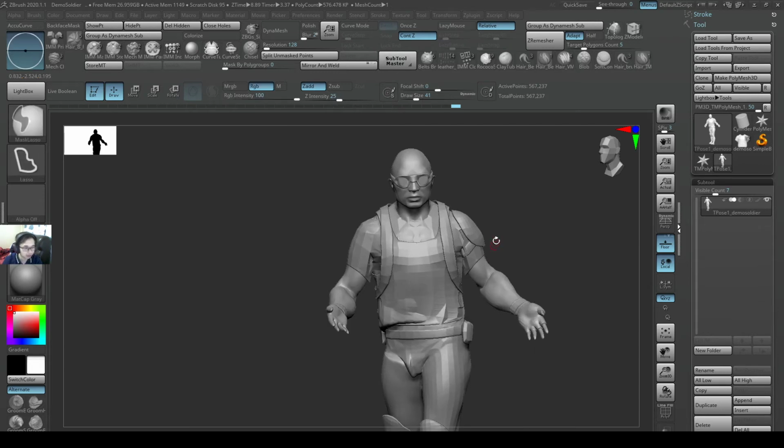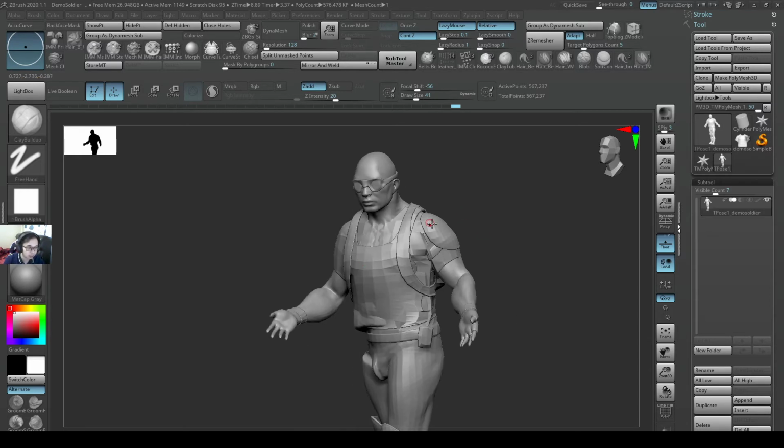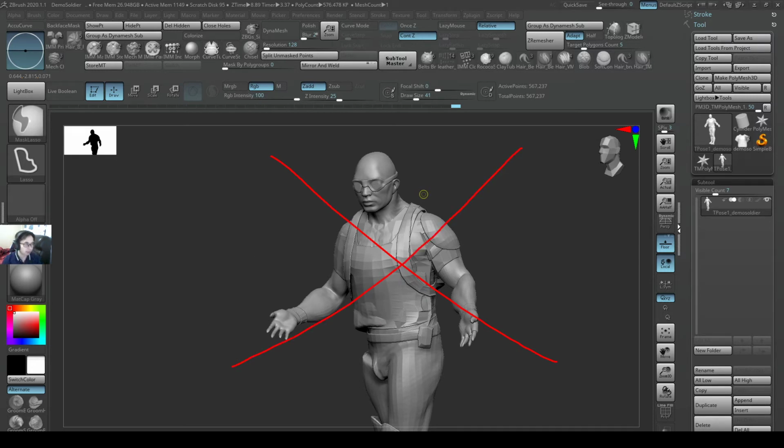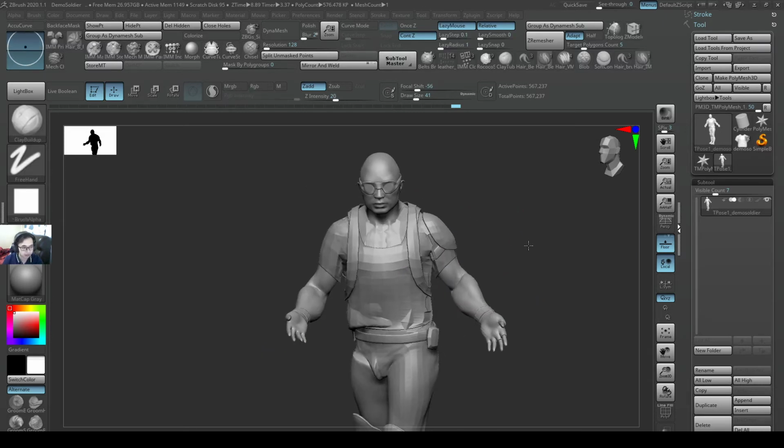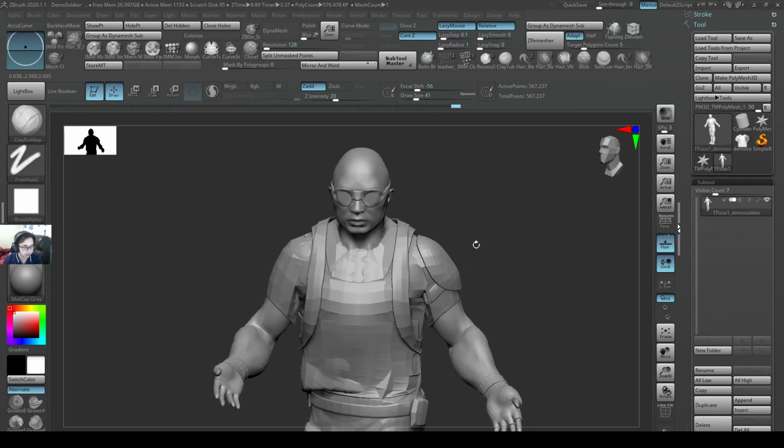It's the same for almost everything I teach you in ZBrush. If you're modeling, you focus on modeling. If you're posing, you focus on posing. If you're poly painting, you focus on poly painting. Try not to do two things at once. In this case, using Transpose Master, you cannot. Sorry, I should use the red one. You cannot do posing and use any kind of brushes together over here, it is a very bad idea. Never do that. It will crash your file, and the pose that you worked hard to make will be totally wasted.